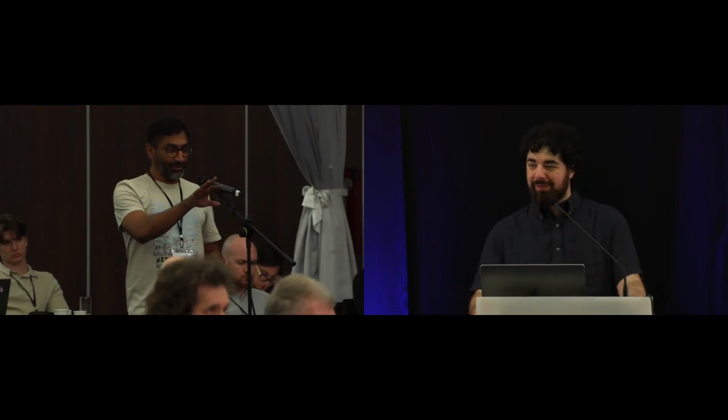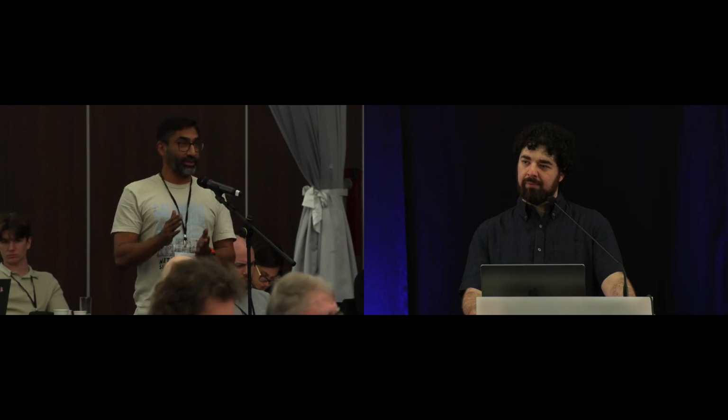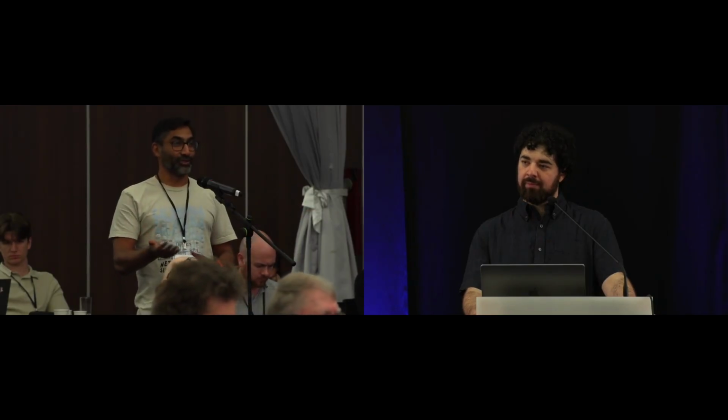Right, right. So where I was going with this, and an important thing to keep in mind from the Zoom comment, is don't think of it as purely, and I think to Shannon's point, I would very strongly ask you to think about this not as a NetDev or a network interface problem. Because, by the way, there are PHYs on PCI, there are PHYs on things that are coming with UVC, UA-Link, blah, blah, blah, that are all going to have this exact same problem. And Ethernet is a bit of an interesting problem because there are famous things like NVLink, which is actually an Ethernet PHY on the bottom, right? So you should be able to see the Ethernet PHY stats the same way. There's no reason for it to be different.